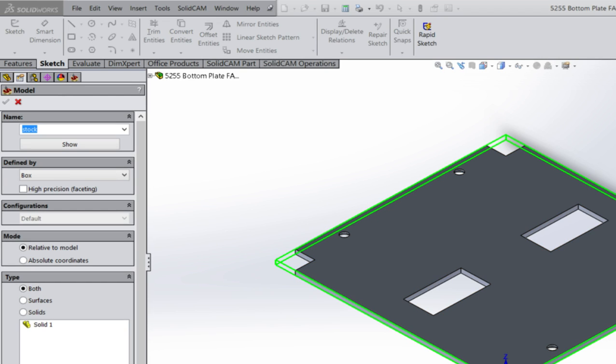Okay, now SolidCam assumed that my stock was exactly the same size as my plate. Is that going to be true? No. You probably would have used what tool to start your stock for this particular piece? It's about 80 thousandths thick aluminum. What would I have done to start this piece? Bandsaw? Which one? Probably the vertical bandsaw. I would have found a sheet of aluminum bigger than this and bandsawed it out.